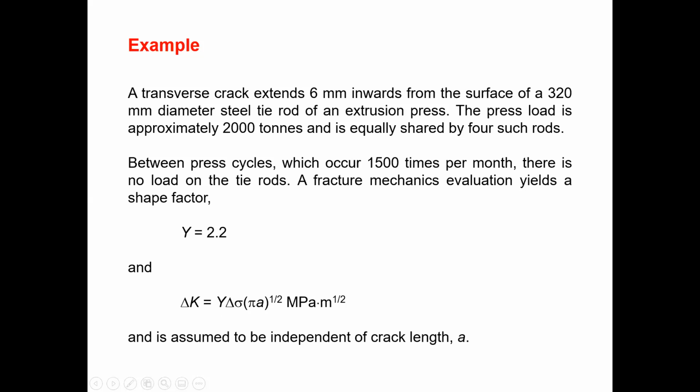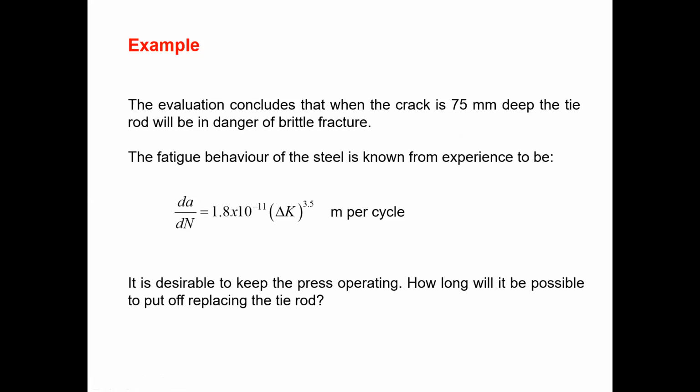Okay. So then they provide more details. The evaluations conclude that when the crack is 75 millimeter deep, the tie rod will be in danger of brittle fracture. So when the crack length is 75 millimeter, it is a kind of critical situation.